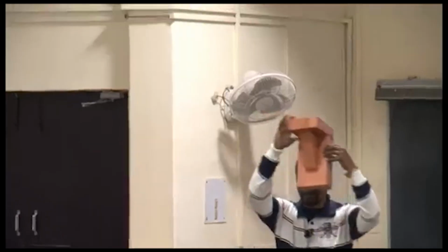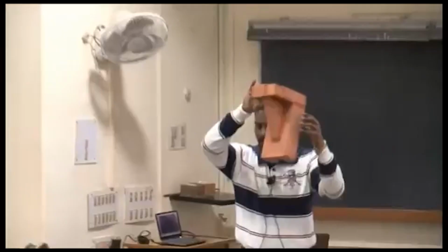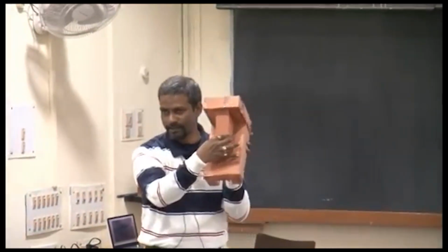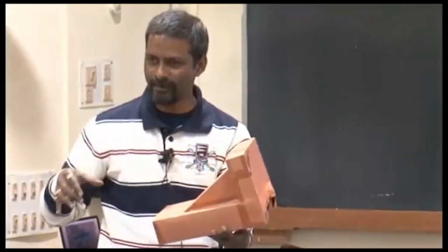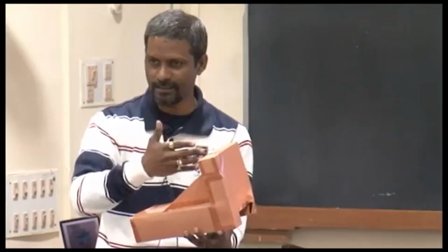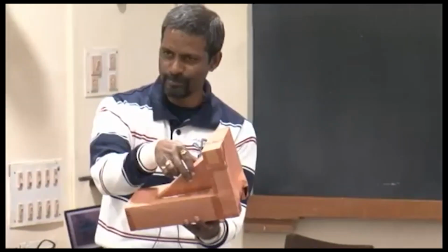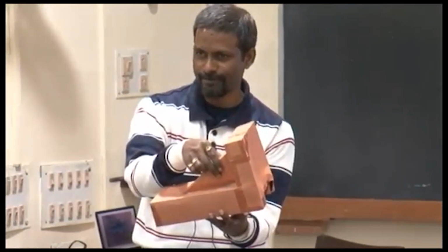Part 1, part 2, they are supposed to be perpendicular. This part is called a rib. It's a triangular feature, it's called a rib. So if I take a section, I just take the rib off, take the section, hatch this platform and this platform, and then, so to speak, put this back.